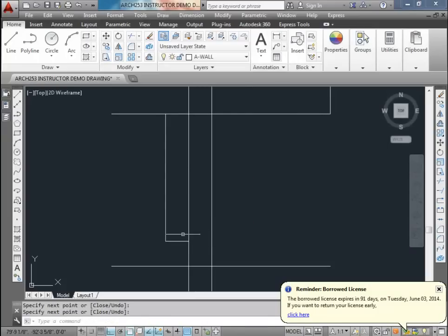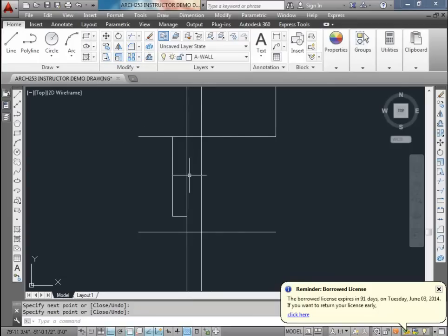So what I did is I just did a little construction line. This is actually going to get me to the inside of the wall. So the way I've configured this is that we have our 2x6 wall, which is sitting on top of the foundation wall. I could actually draw that in right now. The foundation wall is offset 2 inches to the inside of the exterior wall. So this is going to be the foundation wall, the line that's shown dotted right now.